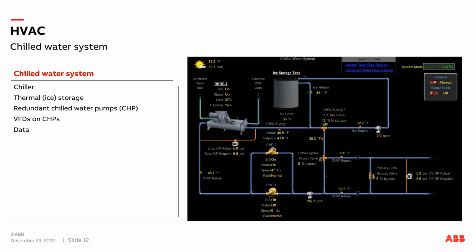There are more simplistic systems where it's just a single air handler. Somebody might call it a DX unit. There's refrigerant, a compressor, and a coil, all in the air handler. It's kind of an all-in-one turnkey solution, a little bit closer to your home air conditioner type system. If you go to your big box stores or your grocery stores, that might be what they have up on the roof. What we're teaching today is based on a chilled water system, which is a little bit more energy efficient, a smarter system. Everything is tied together.